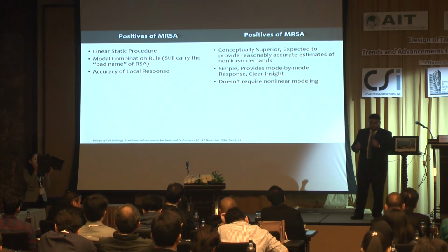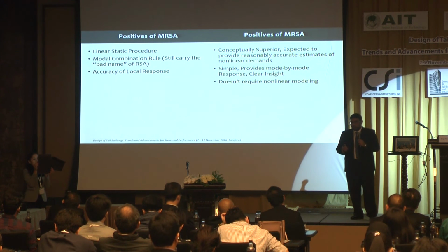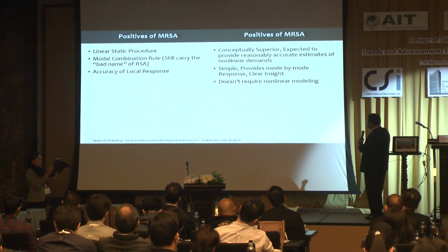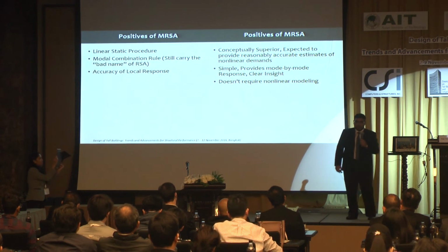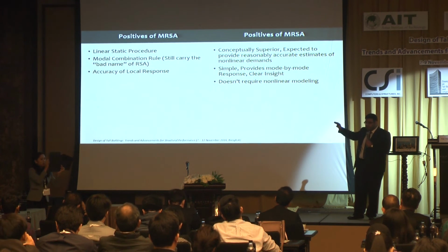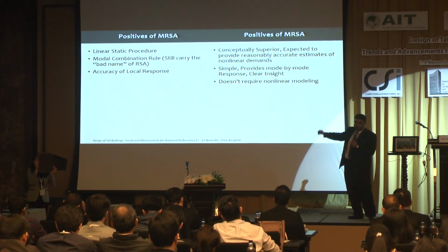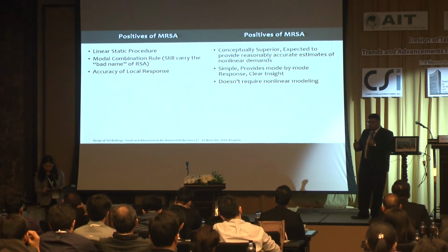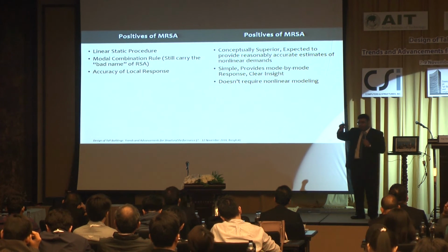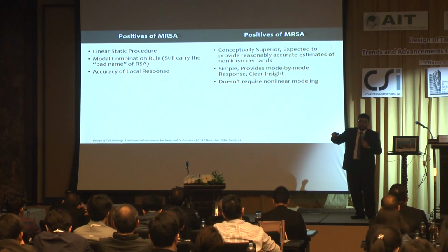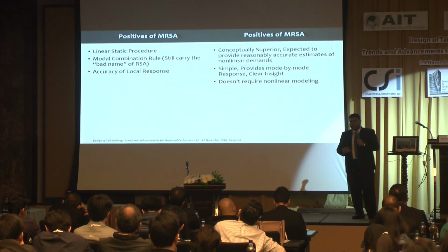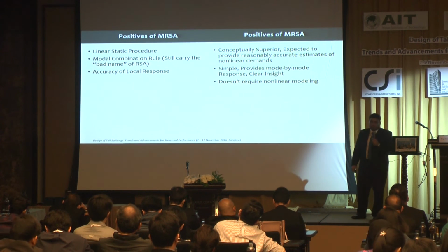As I said, that modal response is the basis. The black box is not the solution sometimes, and it doesn't require nonlinear modeling. This is one of the positive things, that even if we are not able to capture some of the accuracies which we expect, look at the impact this idea can have on practice. If you give a designer that accurate curve of period elongation and additional damping, without knowing nonlinear modeling, he can still get results which are close to nonlinear time history analysis.